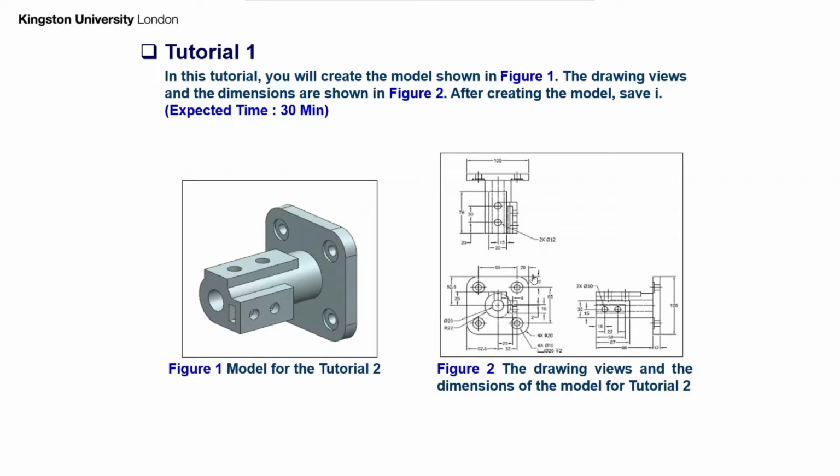Once I make that one, I'm going to extrude it, and then on that face I'm going to start sketching a base of that cylinder and extrude that one. So I'm going to make a 2D sketch of a circle, extrude it, and then apply a hole there and a hole here. Hopefully we're going to try the patterns as well, and then continue with that. So let's open SolidWorks and start making this model.